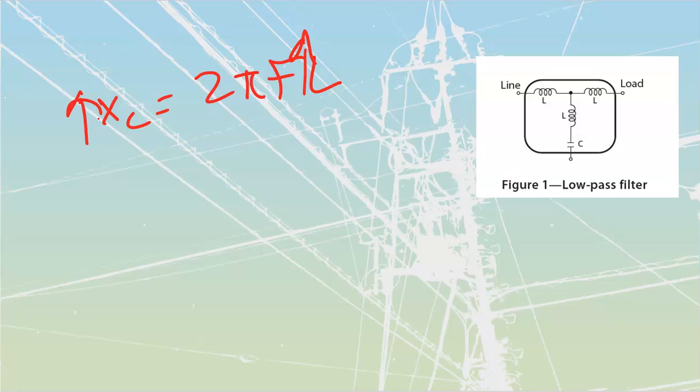Harmonic filters are probably a better method than trying to size your transformers, because if you can take the harmonics out before they reach the transformer, you are then not going to have to deal with it. We don't need to go K factor if we don't need the K, because we don't have the harmonics inside of there.